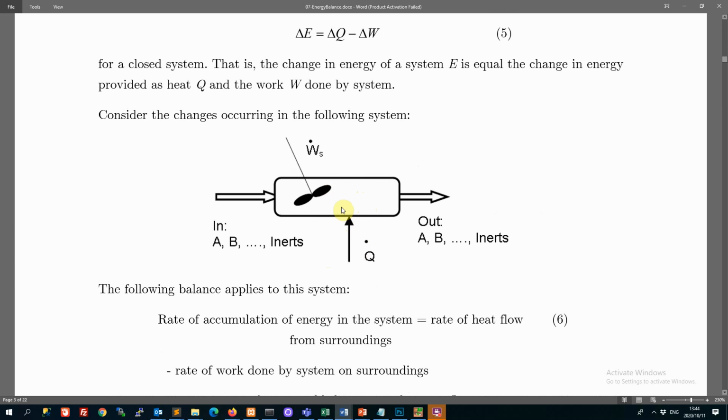And remember, that's not a mass contribution. So we are not injecting steam directly into the reactor. That steam is not mixing with the reacting mixture here. That steam is staying in the coil and exiting. However, across the walls of that coil, that temperature difference is causing thermal energy to be given into or removed from the reaction space.